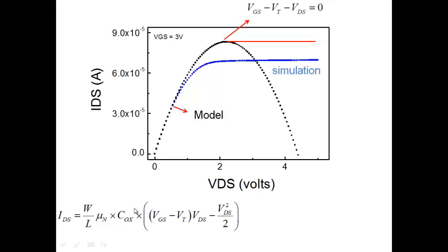Now if I take my current equation and plot it, the current equation is this black line here. It goes here, and at this particular point my channel has become pinched off. After this, I cannot apply this equation anymore, right? If you apply it, it denotes a falling current, so the equation has validity only at this particular point. After that, the moment the channel gets pinched off, the current saturates and you get this particular value. Okay. So this is what I would expect from our simple model here.